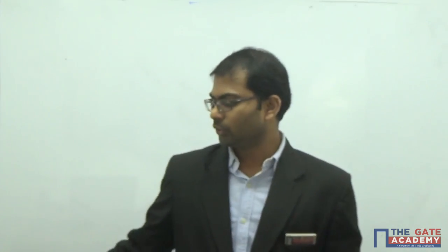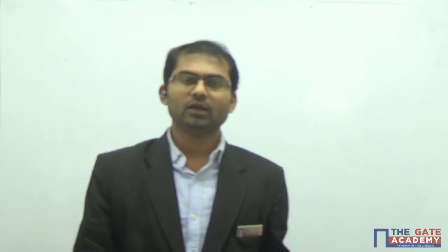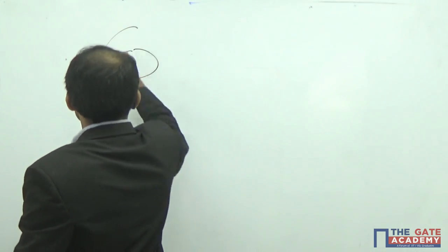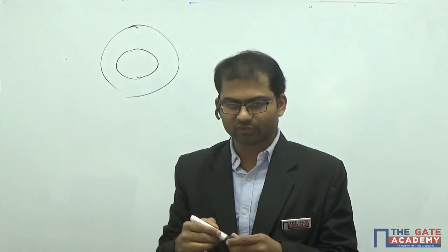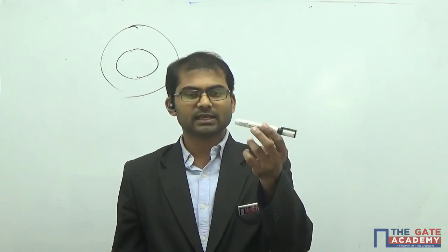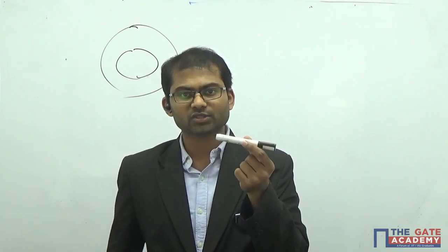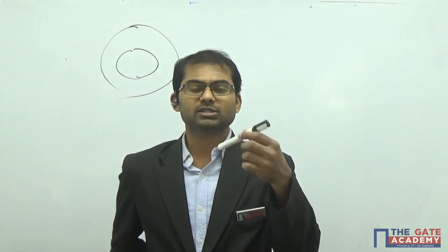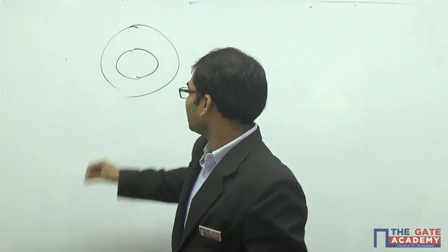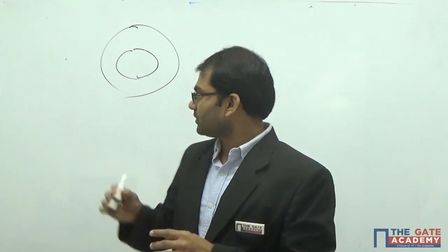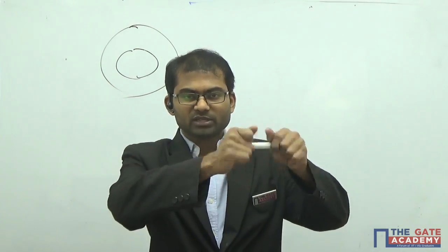So basically only one solution will come, to put two shafts in parallel and create some torsion here. That is nothing but inserting a solid shaft inside a hollow shaft. So the solid shaft is inside the hollow shaft here. This composite shaft is actually looking like a single shaft itself, because from the outer side we can see only the hollow shaft. But inside the gap of the hollow shaft, inside the internal diameter of the hollow shaft, there is a solid shaft of the same diameter, which is equal to the internal diameter of this part here. So this total composite shaft is experiencing torsion here.